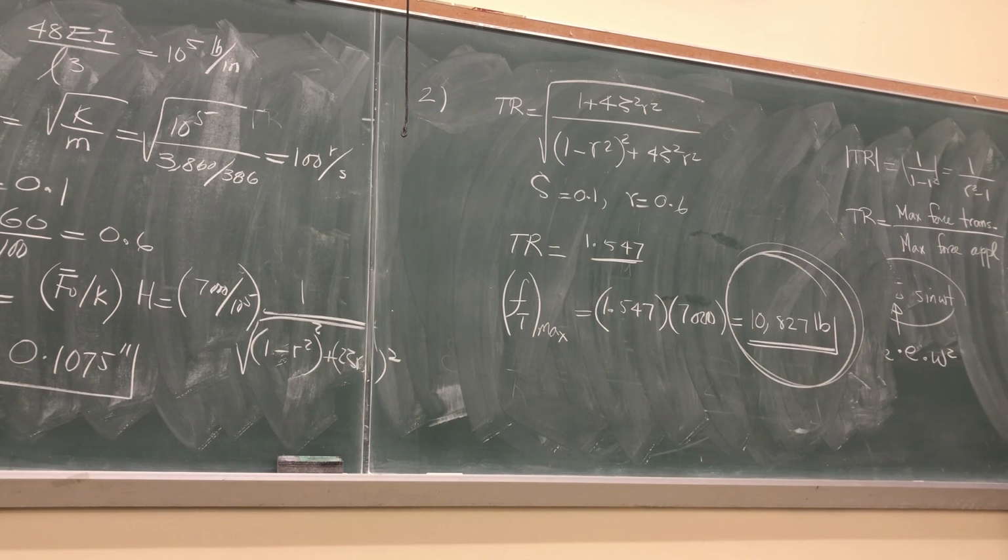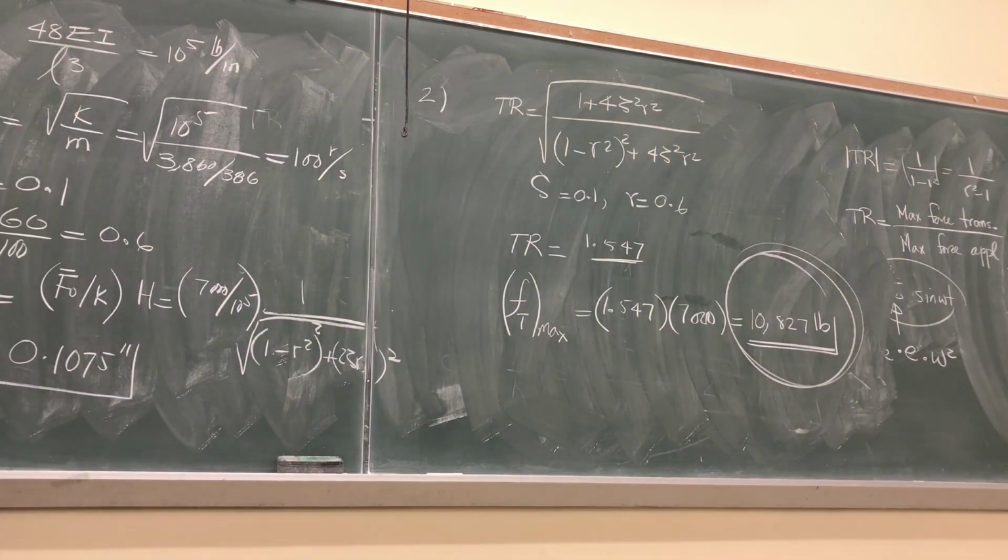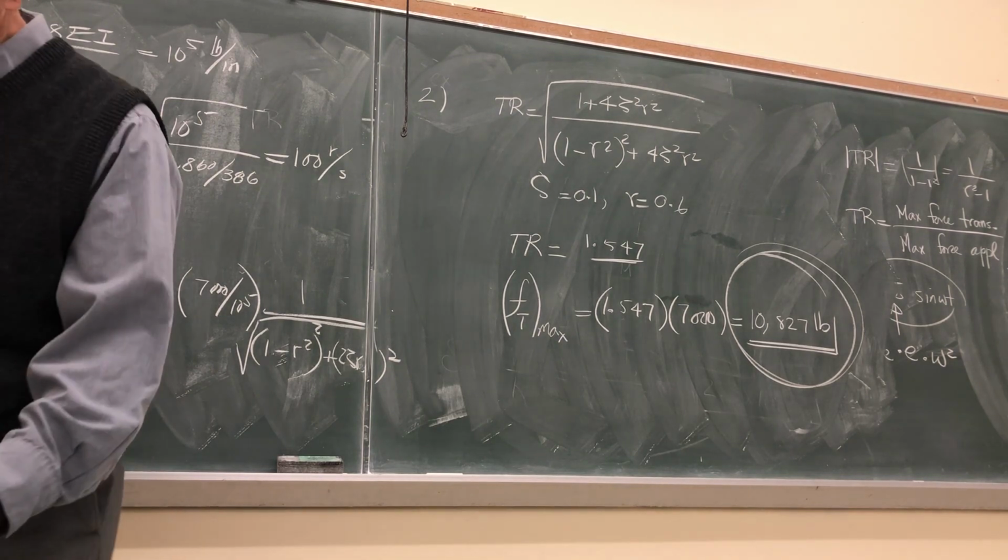So be careful when you put too much load in that laundry machine, depending of course on what kind of foundation it is sitting on. When you go and buy some platform, don't just consider the weight of the machine. You need to know its frequency of operation to know how much force it exerts on that foundation. Okay. So a simple little problem, but I thought it would be practical.